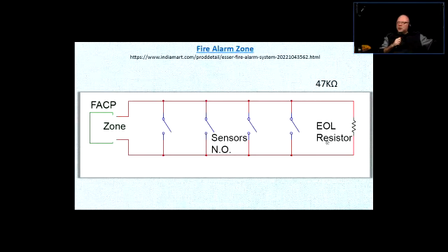It's not going to be able to. So recognize the condition. You need to have end of line resistors at the end of line. Nomen omen, which means the name defines its functionality. It's a Latin expression. So it should be at the end of line. Now, what happens if something is triggered? As opposed to the security alarm, the switch will be open upon a condition.